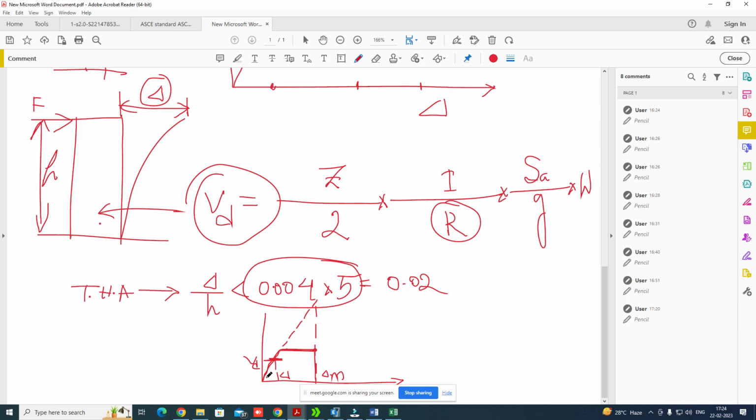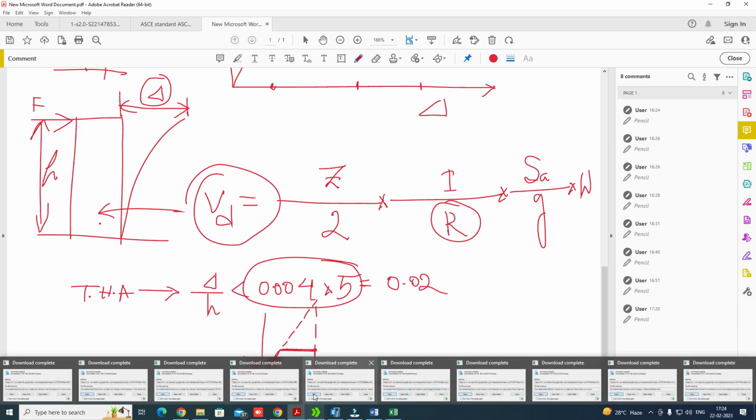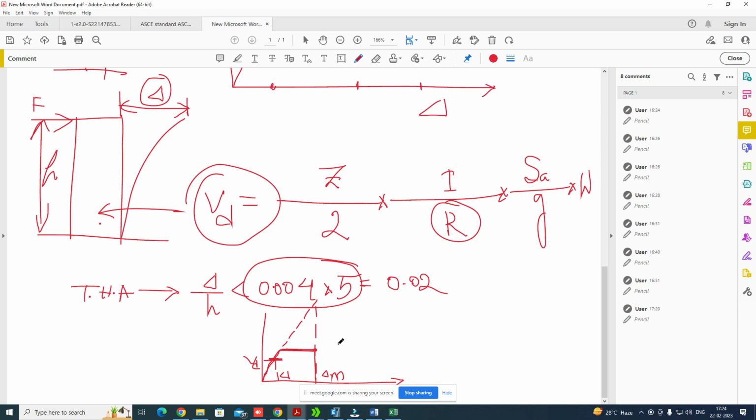But when we consider the nonlinear time history analysis, you do not consider your structure with reduced base shear, you consider the full hypothetical structure, meaning full nonlinearity you consider. But as you see, the maximum displacement is the same in case of both the hypothetical structure and the actual structure. So because of this you have to check for the total displacement which can be obtained, not this reduced displacement. This is the total displacement which can be obtained, and this should be checked for this limit.